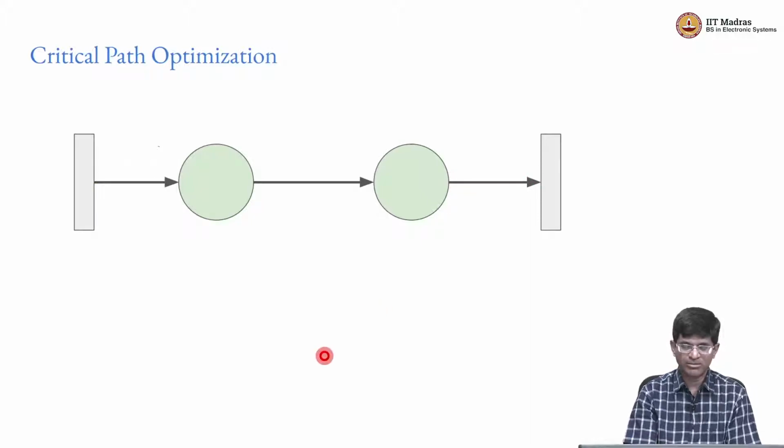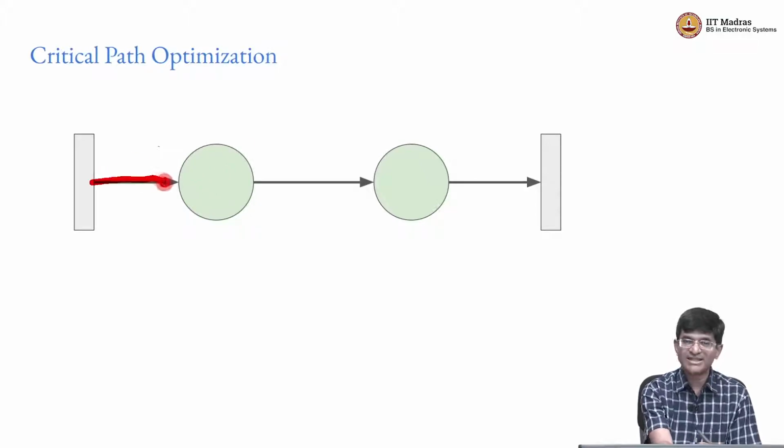Now in practice it's not as simple as this. Each of these blocks, this circle as well as the other circle, is going to correspond to a number of different gates. There may be AND gates, OR gates, full adders, NOT gates, and so on, that constitute this, which also means that it's not just one signal that's coming in here, it's a whole set of different values. So when I draw a register over here, what I actually mean is a sufficient number of flip-flops so that all the signals that are coming in over here are registered, are captured at this point, and there is a clock that basically determines when all of those signals come through and are ready for starting the computation.